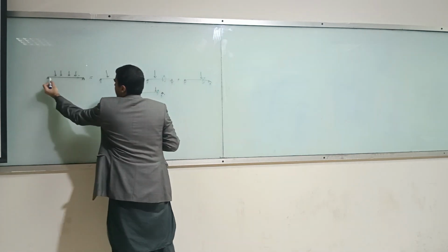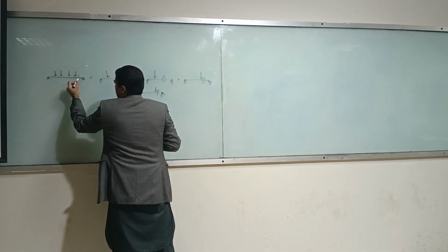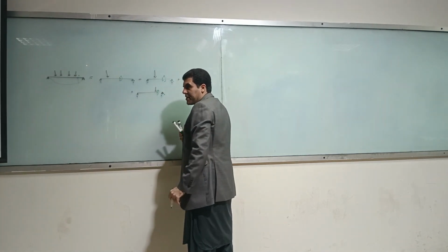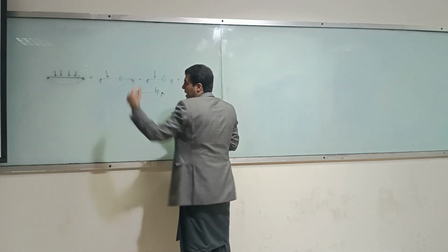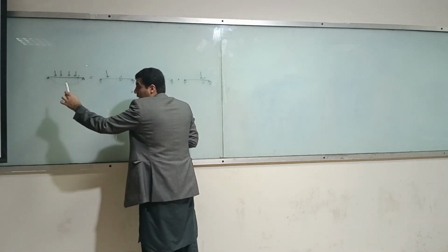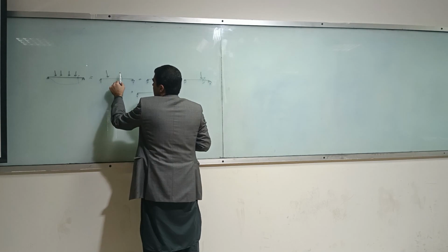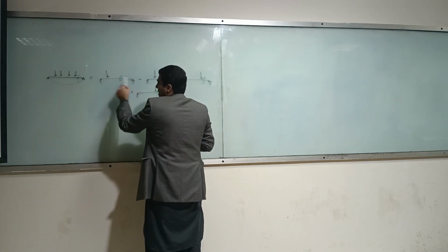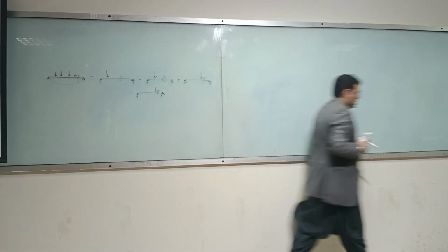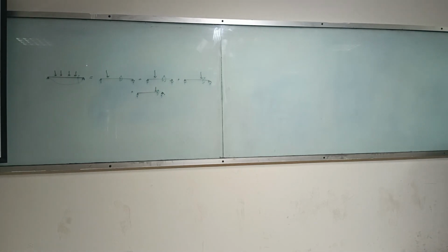If I'm interested in finding out the deflection over here, the overall deflection would be equal to the sum of the deflections of the independent loads. Or if I'm interested in finding out shear or bending moment of this structure which is subjected to all the loads, I can have it decomposed into these beams, independently find out the moments and add them up, and I can find out the final moment. Okay, any question about this?